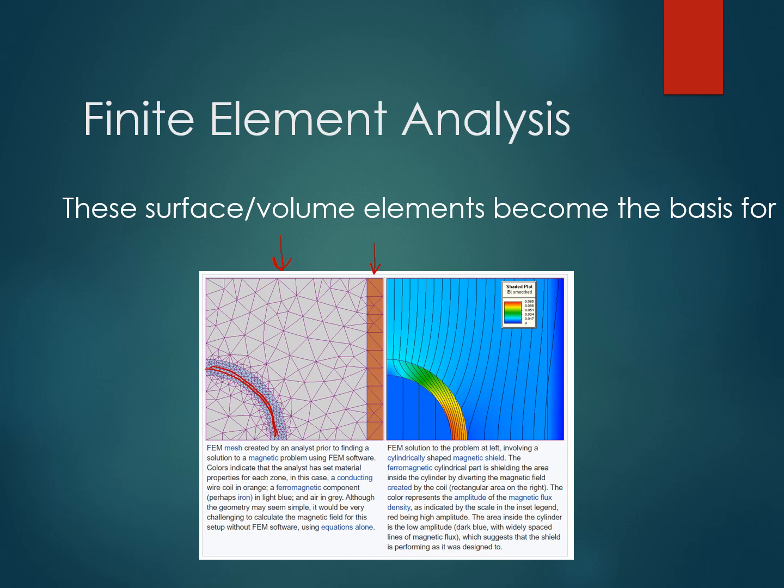Usually this is a piece of just iron, and then air that's surrounding it. So you see that when we've got surfaces that are close together, or two different kinds of surfaces that touch, we want a much finer mesh because those interactions are going to be much more complicated. Whereas out here in just the medium of air, we have a relatively coarse mesh